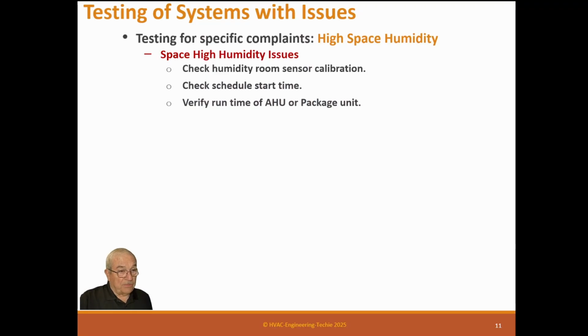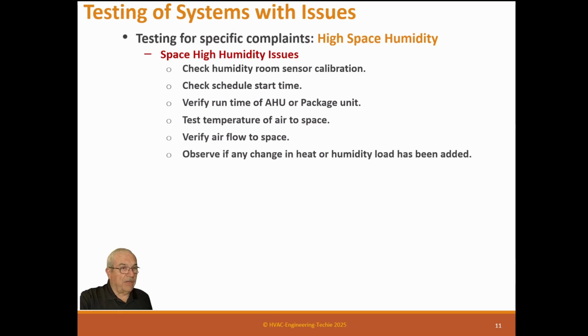Now, you can't reduce a package unit down below 25% or so of design airflow because you can damage a compressor. Test temperatures of the airspace, because temperature and humidity act together. Verify the airflow of the space. Observe if any changes in heat or humidity load have been added.